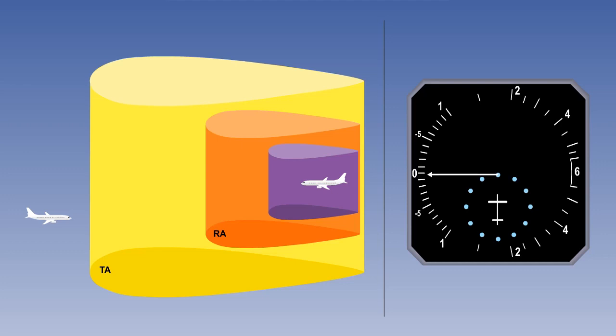The limit time is different depending on aircraft altitude, which is linked to a sensitivity level, and the planned separation value is between 300 and 600 feet, increasing to 700 feet above flight level 420. If any aeroplane enters the first bubble, then a traffic advisory is displayed to the crew in the form of an amber circle.